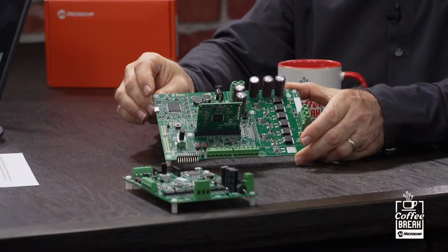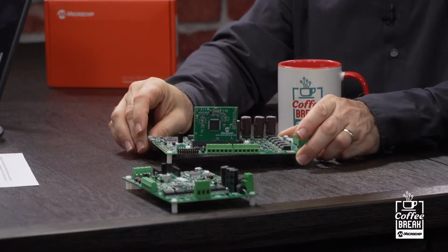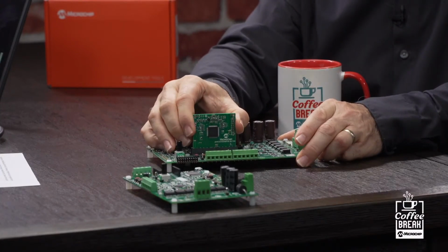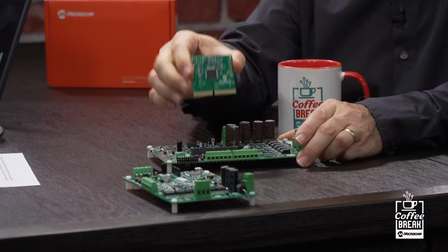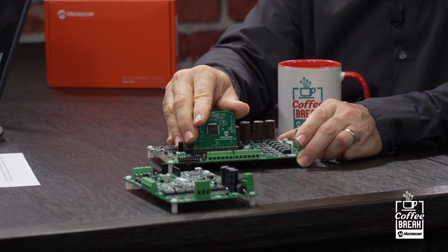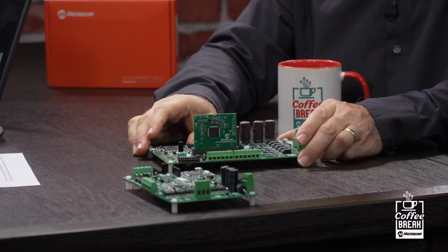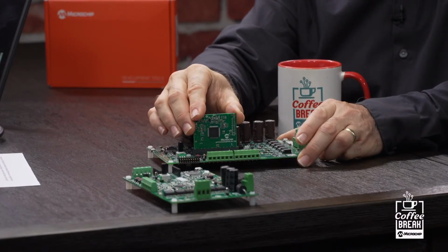Okay. And then one more question I have for you is, how is this new board different from the MCLV2? Well, that's a good question. This MCLV 48 volt 300 watt is actually the replacement for the MCLV2. It's more modular in that we've gone away from a square PIM to this dual inline DIM because the insertion force for the DIM is so much easier to insert and to pull out of the board than the square PIM was. And also, this has more pins. It's 120 pins versus 100 pins.